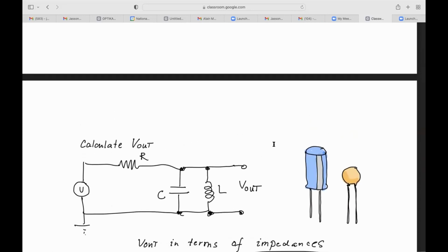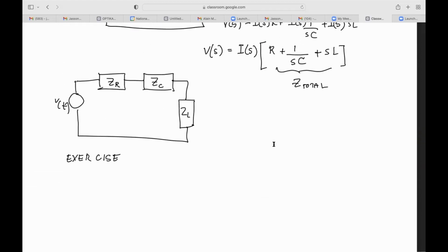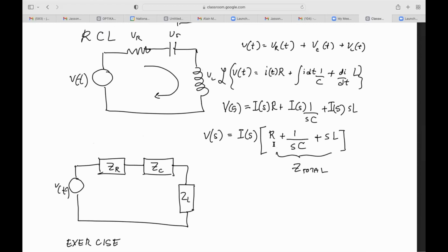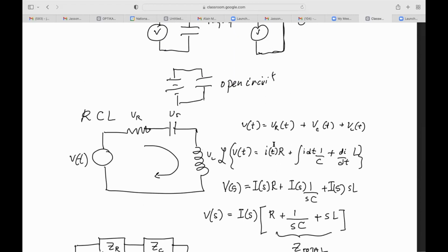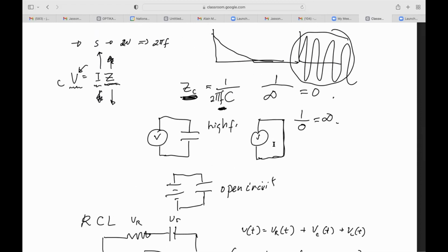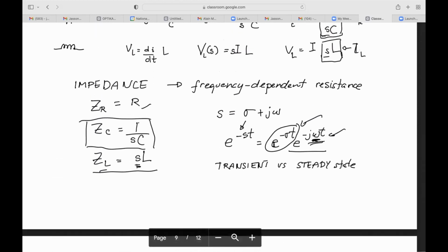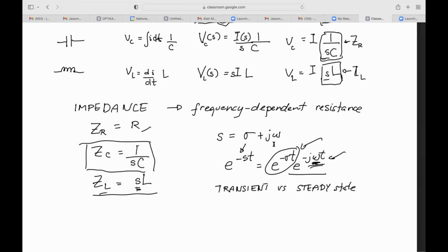To summarize, we will have an activity. The first activity is the input-output curve because we're going to make a rotation sensor and we need the input-output curve as our calibration curve to convert resistance, which becomes voltage, to angle. Note that when you get that input-output curve, of course, it's at steady state. With resistors naman, with potentiometers naman, the steady state is once you're finished adjusting it to that angle, then that's it. Steady state na yon, right?